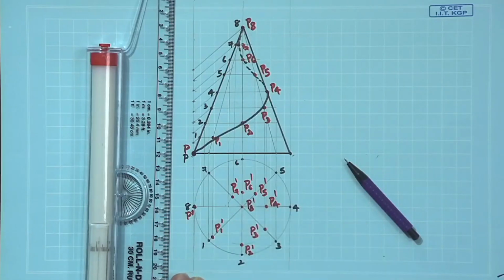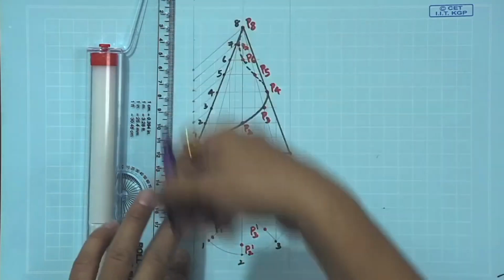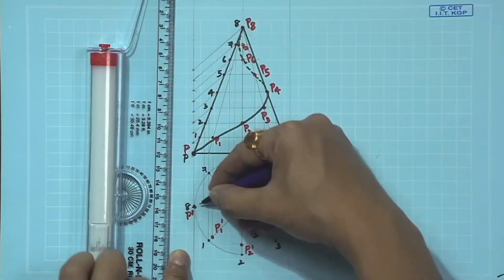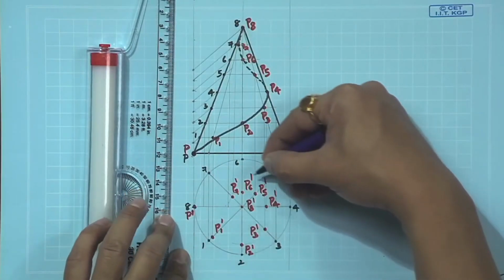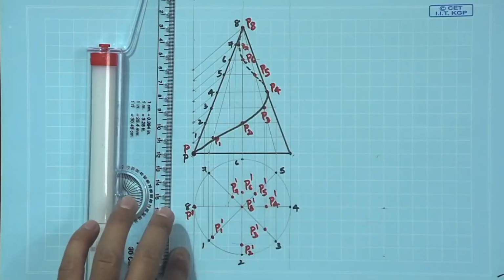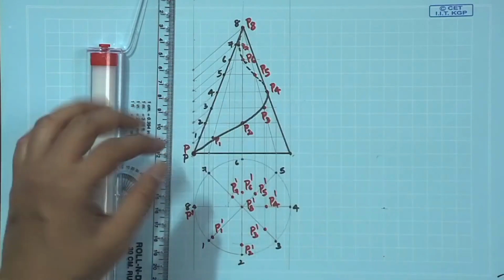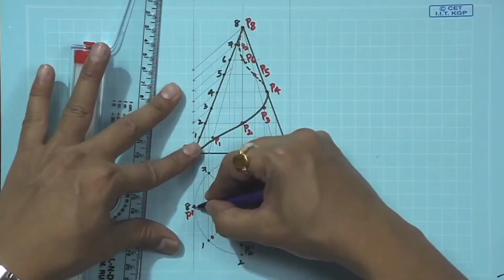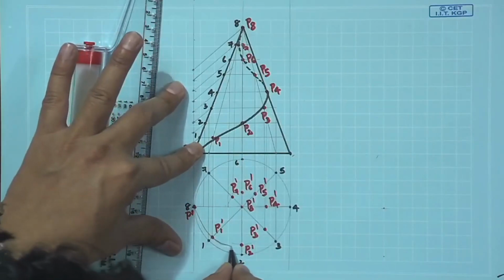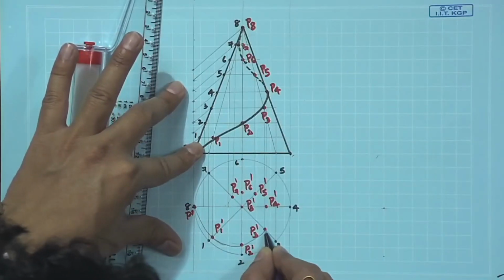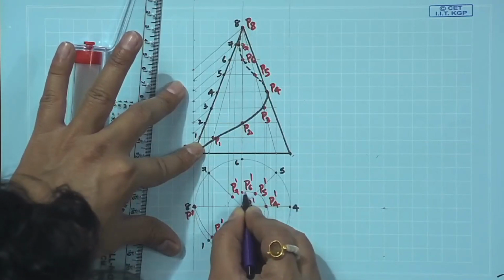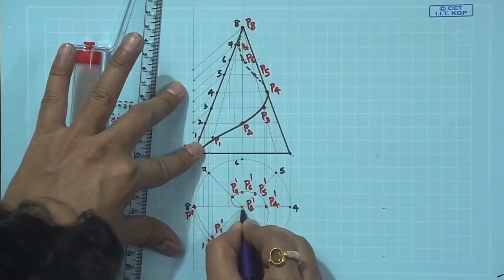Now, join these, because we are looking from the top view in that direction. So, the entire curve will be visible. On this view it will be a continuous line. From the top we are looking and trying to show it on this horizontal plane. So, join by a smooth freehand curve which passes through P4, P5, P6, P7 and P8.